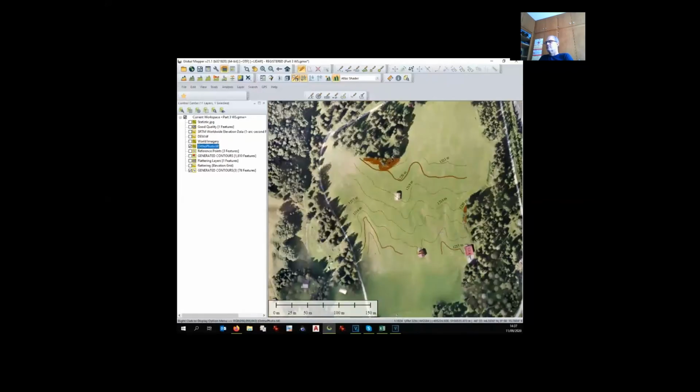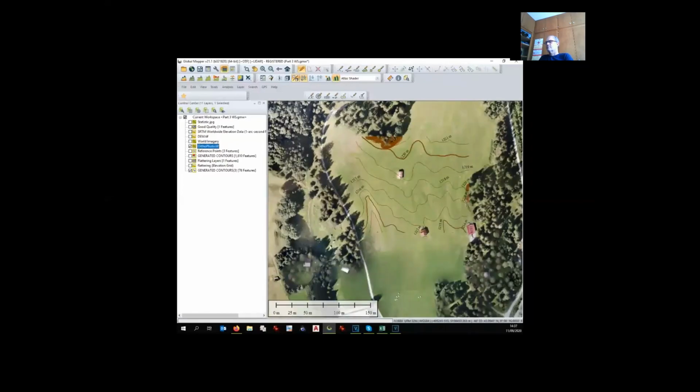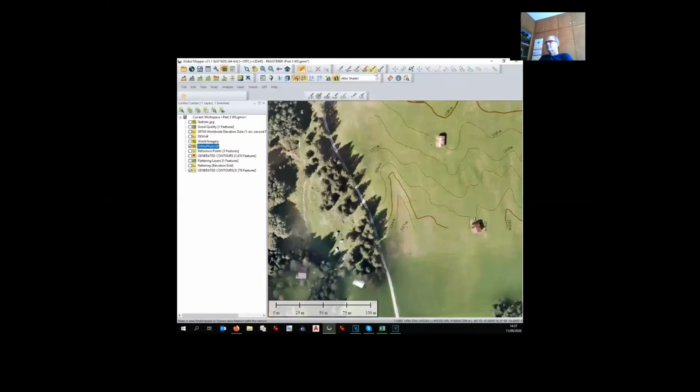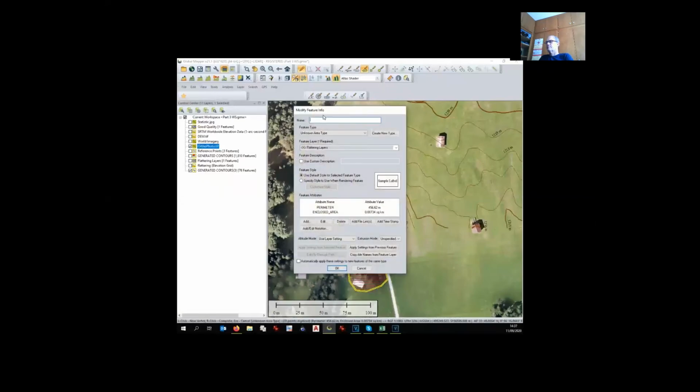Let's assume I want to eliminate this forest here. I have to create an area around the forest, keeping in mind that the border of my area should touch the ground. If it doesn't touch the ground, it will not receive the right elevation. I include this building along the road. Now I want to flatten all this area. Fine.